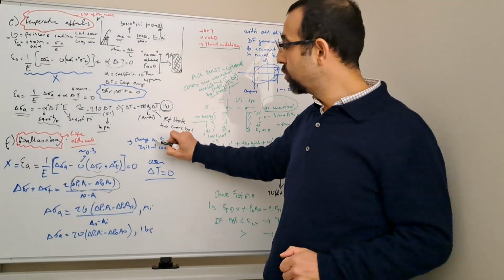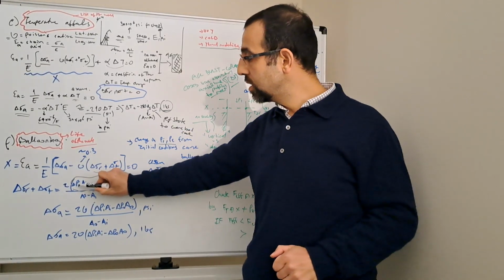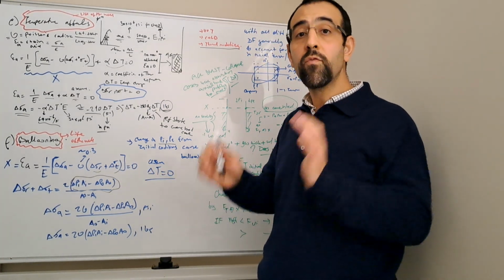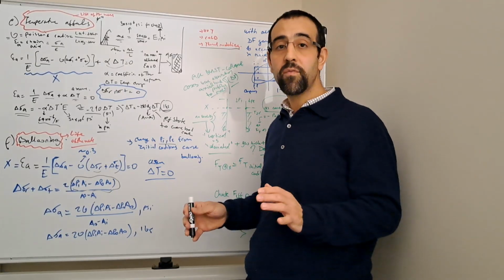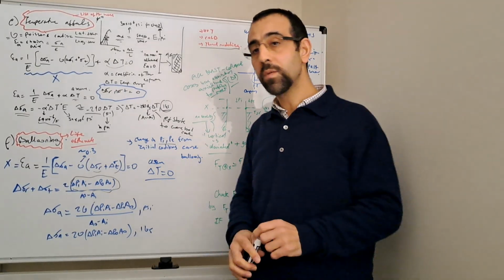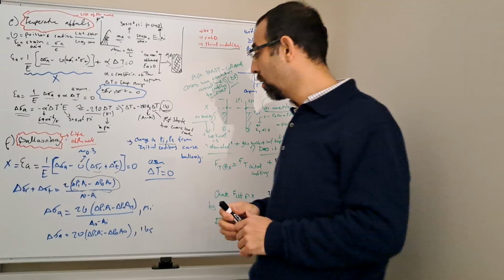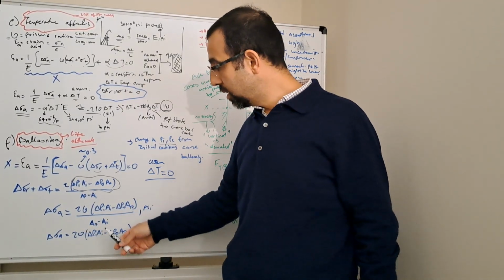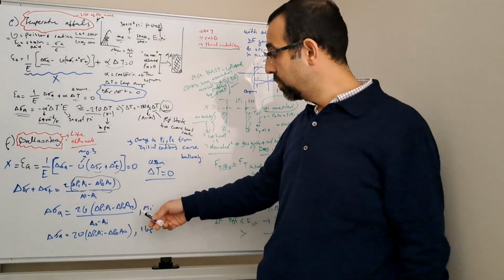So we are dividing by the cross section to get psi. And here I put a note saying that the change in the internal pressure and the external pressure is from the reference state. What's our reference state? It is the locked-in tension profile, which I talked about on the first page. In order to get into pounds, we simply multiply by the cross section.